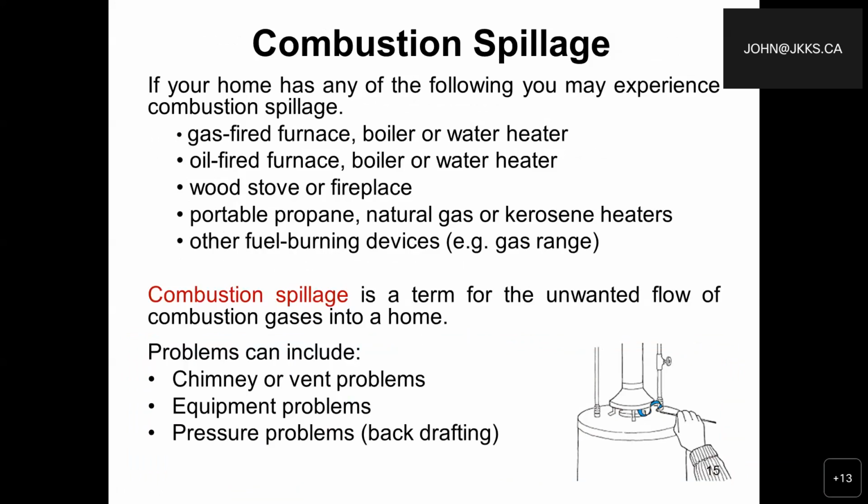And you can see I provide a little bit of a list there. Normally, these combustion products, which can include both visible smoke and various invisible gases, are vented to the outdoors through a chimney or some type of vent pipe. Some people call those the flue. Unfortunately, they may on occasion escape or back up into your house, where they could raise a variety of health and certainly other concerns. As I mentioned, carbon monoxide could potentially kill in the worst case of scenarios or make people very, very sick. Annual inspection and certainly periodic maintenance, to me, is very critical for all combustion appliances to